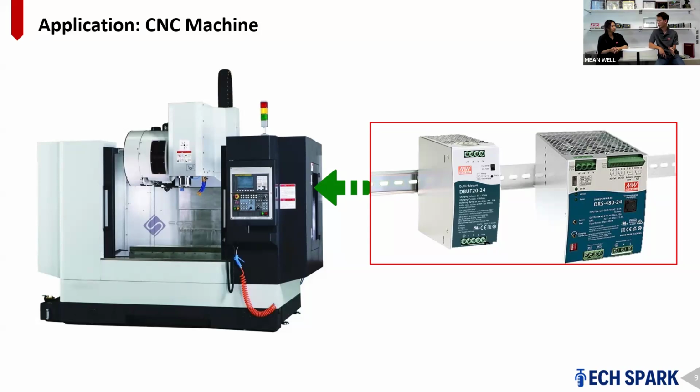Sure. Any interruption or inconsistency in the power can lead to errors in the machining, resulting in defective products. So buffer modules ensure the machines operate smoothly without interruptions, maintaining the quality of the workpiece. On the other hand, the CNC machine contains sensitive electronic components that can be damaged by voltage spikes, surges, and voltage drops.